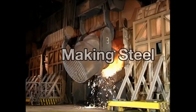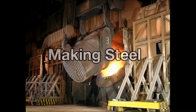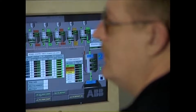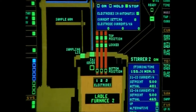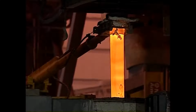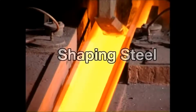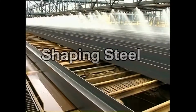Making molten iron into steel involves removing some impurities, such as carbon and silicon. In other words, it has to be refined, and this is done by blowing oxygen onto it. Other elements are then added to adjust the steel's composition, making it suitable for any one of the thousands of purposes for which it could be used. The molten steel is then solidified before being formed into a suitable, usable shape. Well, that's the quick answer.